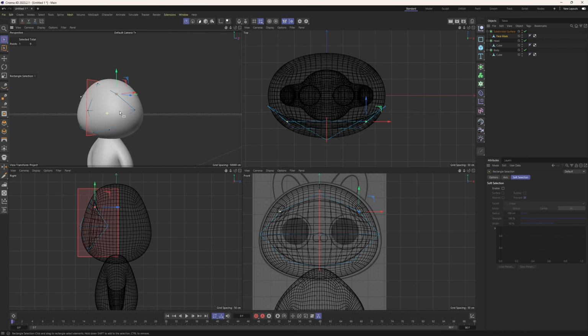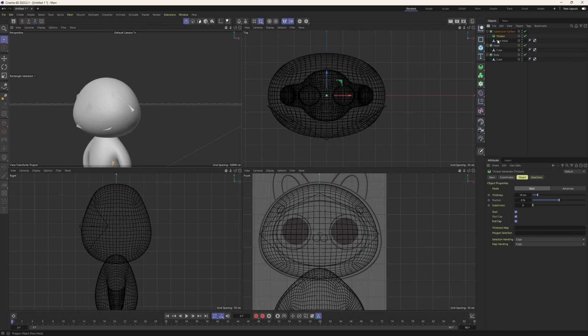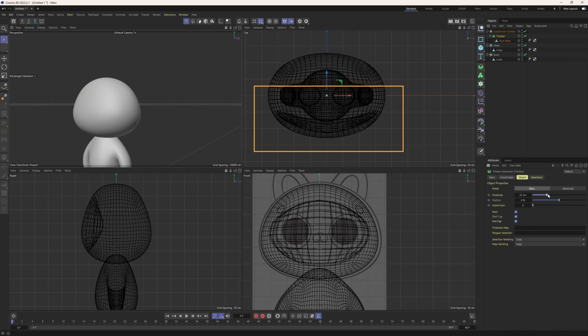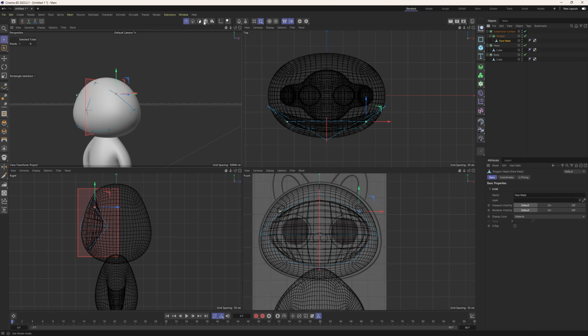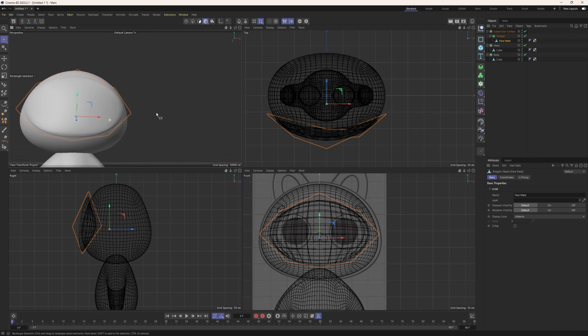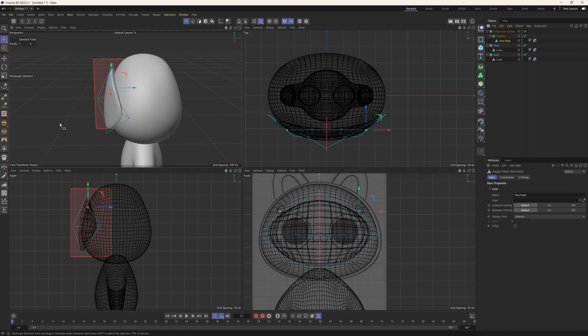It's very flat. We need to make it thicker, and we grab a thicken modifier, which we put inside the subdivision surface modifier, and put our face mask cube inside it. Let's add some thickness. Now we take our cube and push it forward to see the volumetric mask. We can see that some edges are not fully aligned with the face. I move them a little bit backwards until I see that the mask nicely comes out.